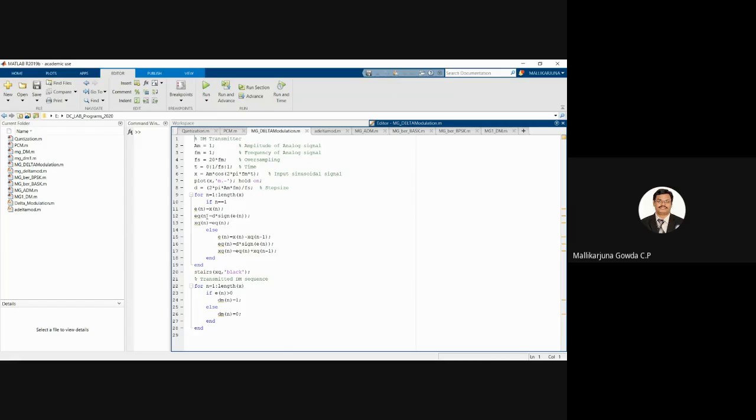That is the output of the quantizer, the 1-bit quantizer. Means, when the difference is positive, I should get plus delta. When the difference is negative, I should get minus delta. Is that clear? So I am assigning that value to the quantizer output, Xq of n is equal to EQ of n. This is when n is equal to 1.